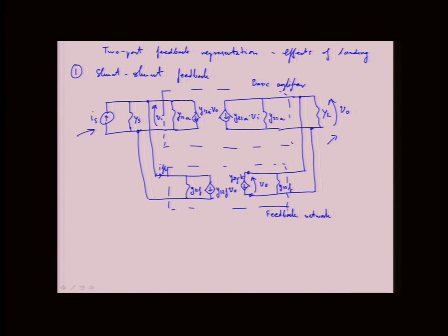Okay, so now that we've added these things, we have a complete picture of both the bilateral signal flow through the amplifier as well as the feedback, and the loading that the feedback, in terms of impedances or admittances, will impose on the main amplifier path. Now, if you want to do some math exercises, you can write out the nodal expressions for this and solve it. You'll see that even for very simple topologies, it gets very involved.